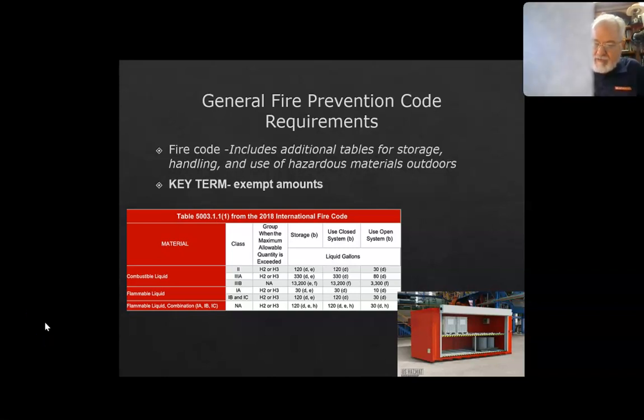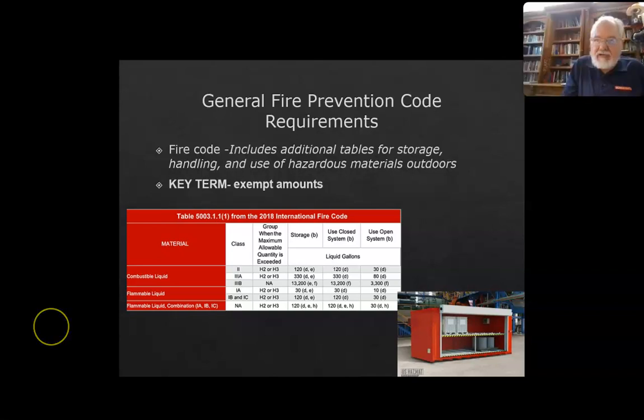Step 2. The fire inspector should take the 3 lists of materials and determine the quantity of each hazardous material that is present in the building and its locations. Step 3. The fire inspector should now divide each list into the hazardous materials that are solid, those that are liquid, and those that are gases. Step 4. The fire inspector should determine on each list which hazardous materials are in storage, which are used in open systems, and which are used in closed systems.